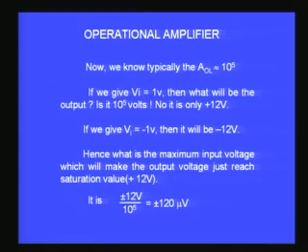So, we can therefore try to look at what will be the range of input voltages for which I will get amplifier behavior, well defined amplifier behavior, which is characterized by the equation V output is equal to AOL into Vi, which I showed you already.